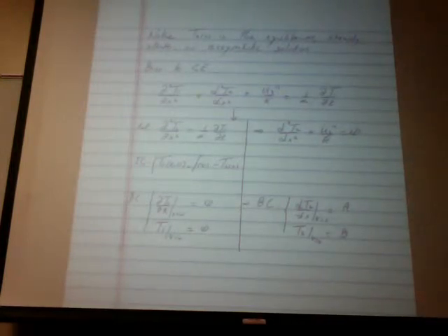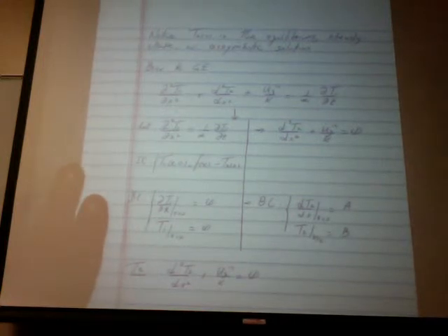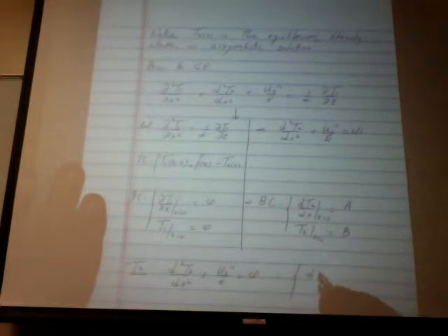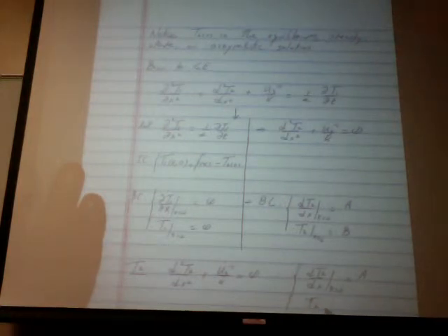Alright, so the T2 problem looks like the second derivative of T2 with respect to x, plus UG triple prime over K, which is a constant, or we are given a constant. It can also be a function of space, as you mentioned, but it would just be a matter of integrating it twice and finding its solution. Subject to dT2/dx at x equals 0 is equal to A, and T2 at x equals L is equal to B.